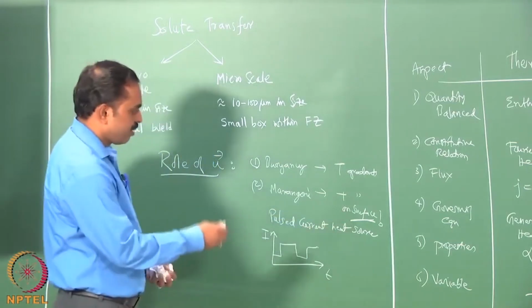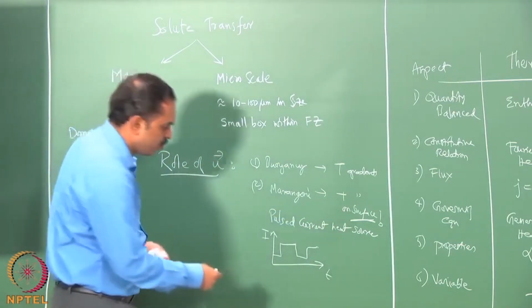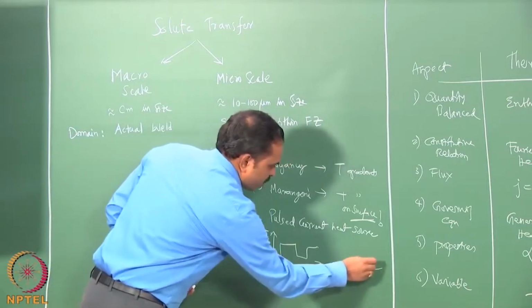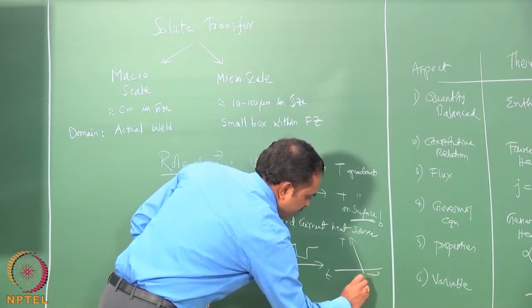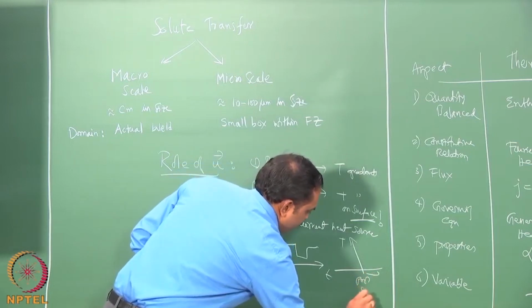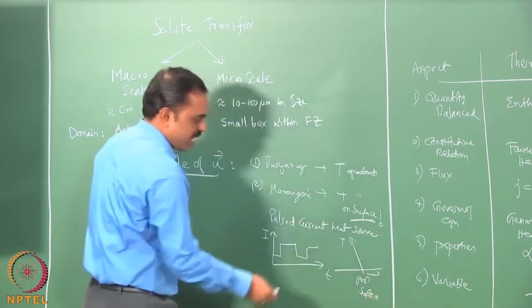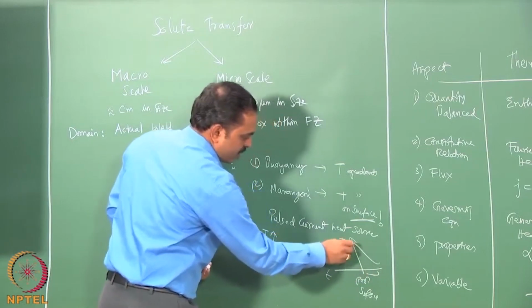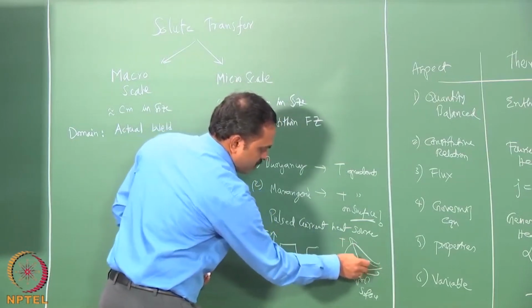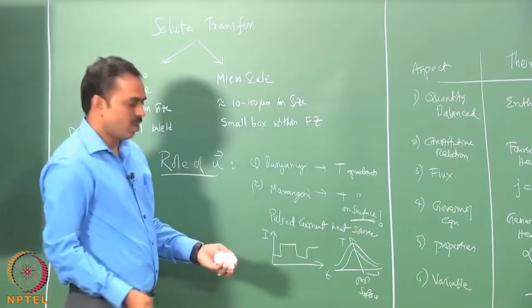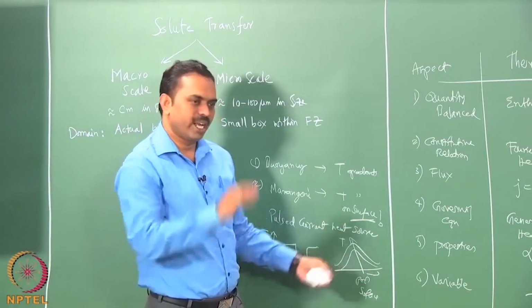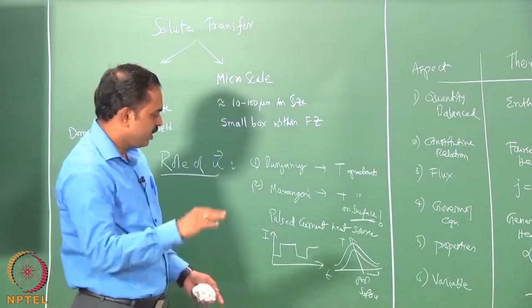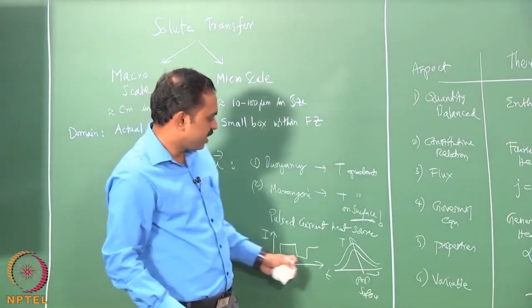In other words, the temperature gradient on the surface of the pool, if you were to look at the temperature as a function of distance on the pool surface, you would see that it may fluctuate between 2 appearances like this, sometimes sharp and sometimes shallow, and it can keep fluctuating between these two as often as the pulsing frequency.